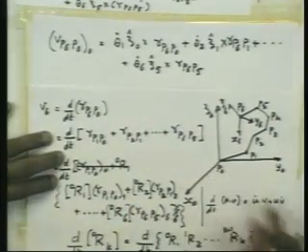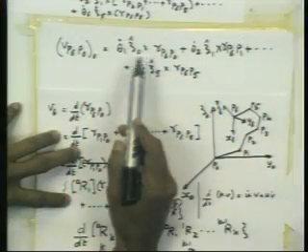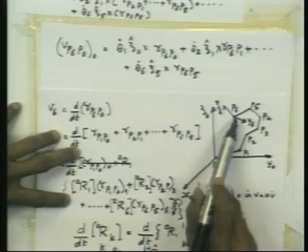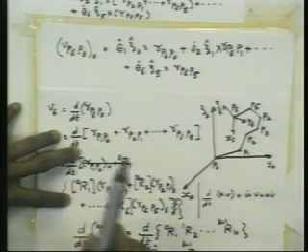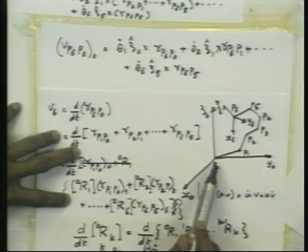So if you come back to our original picture, this first term you can imagine as follows. This is the linear velocity imparted to this point by holding all these joints as rigid, as fixed, and rotating only this joint with an angular velocity theta 1 dot.